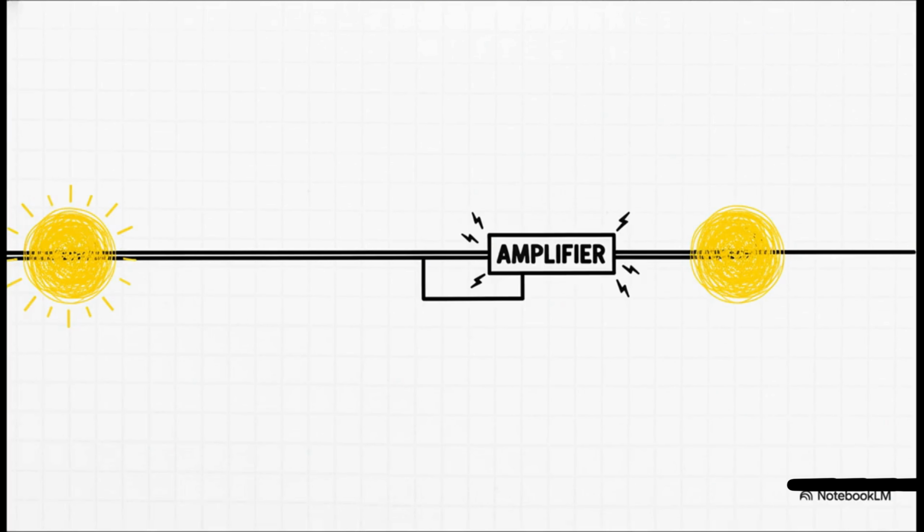Yeah, there's a name for that problem, attenuation. Even in super pure glass, the light signal gets weaker and weaker over long distances. So, the solution is to put amplifiers, or repeaters, every 100 kilometers or so along the cable to give the signal a boost. And you're probably asking, how do you plug those in at the bottom of the sea? The answer is pretty ironic. They run a thin copper wire the entire length of the cable, carrying old-fashioned electricity to power the new-fashioned light.